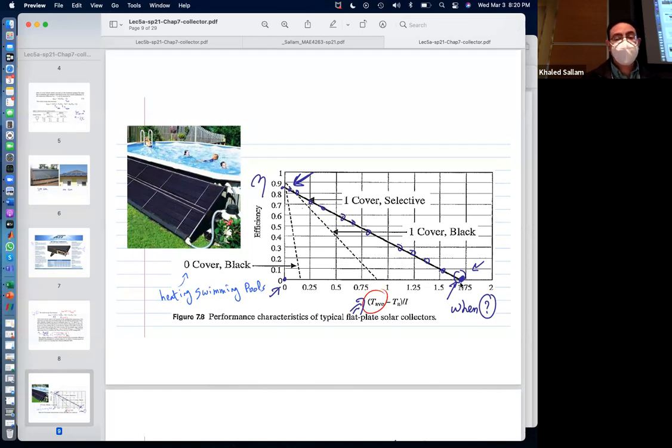What is that scenario? Well, if you have 0 efficiency, you will probably have to use something else to supply, right? So, of course, if you have a solar system, you need to have a backup. But how strong is the backup? Should we have a full natural gas heater standing by in case the solar heater is not working, or should we have a small electric auxiliary unit that can just help a little bit? Probably a small heating unit that's not designed to work all the time and just supplies the difference, right?